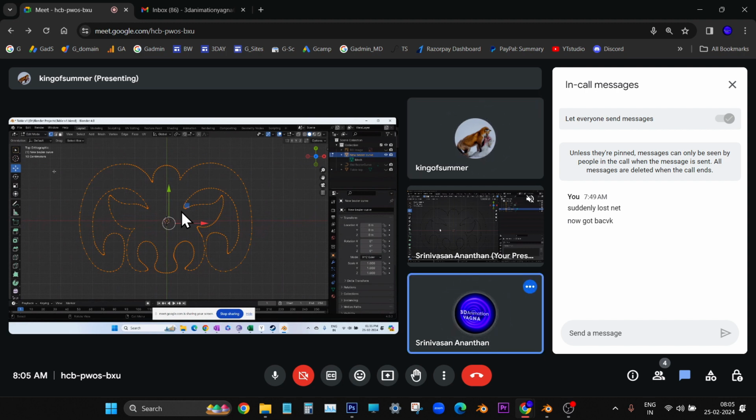Okay, fine. Now these many vertices we don't want. So what should we do? We have an option for that. It's called decimate. We cannot delete them manually. So what we have to do? There is an edge menu in the top right side. There you see unsubdivide. Subdivide means it is becoming more. Unsubdivide means it is becoming less. Now don't click anywhere. You see in the settings, unsubdivide settings, it is 2.